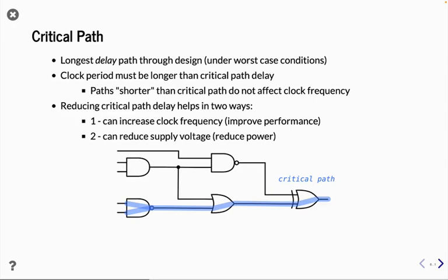And so we often hear people talk about longer or shorter paths, talking about how much time it takes for these things, but that time is often strongly correlated with distance or more logic elements. So in this example, hypothetically, we're saying this path that goes through 3 gates is going to be a critical path for this particular circuit over here, right? And for whatever reason, this path takes longer than perhaps going through here. But maybe this wire is longer, and that's the reason why it's slower.